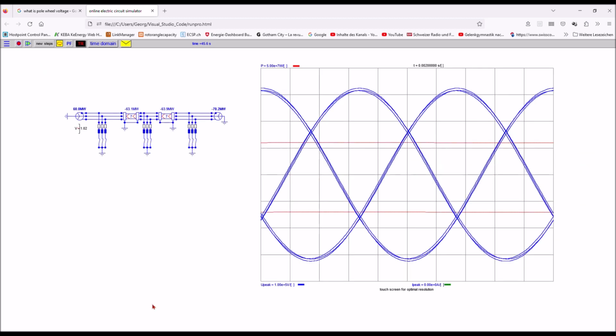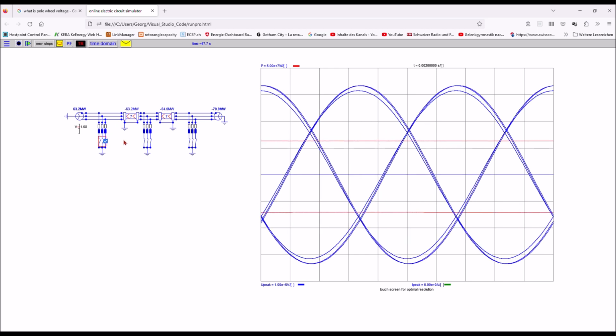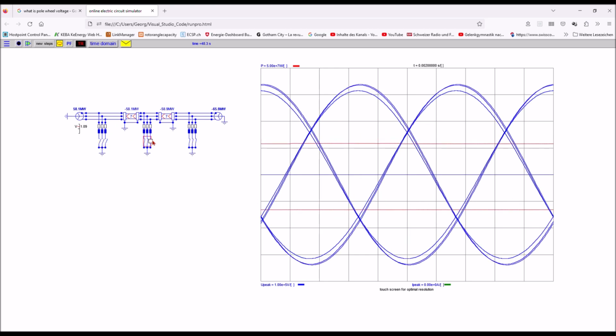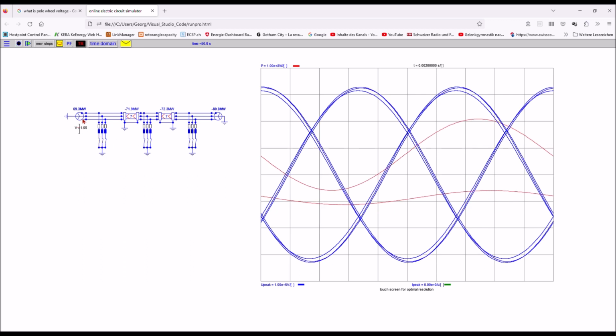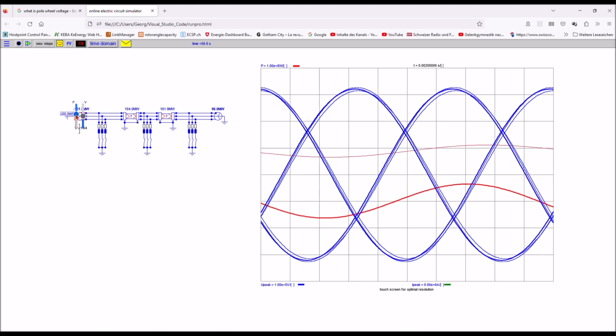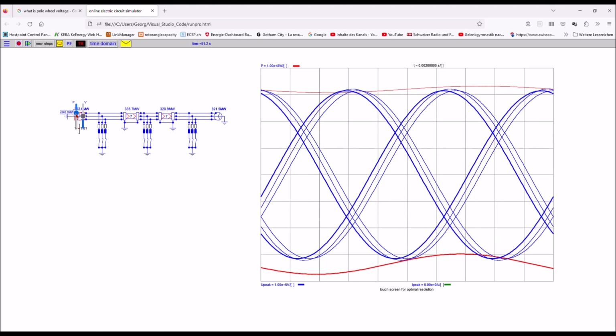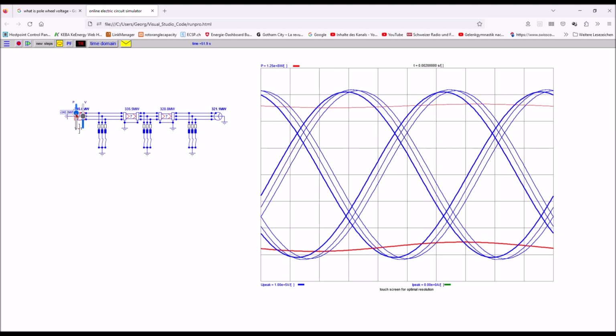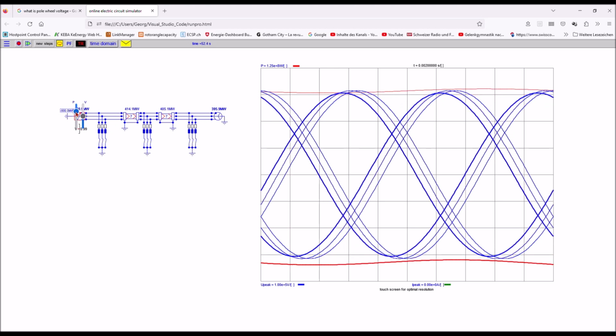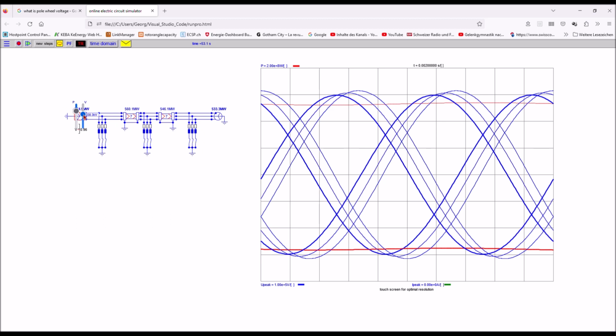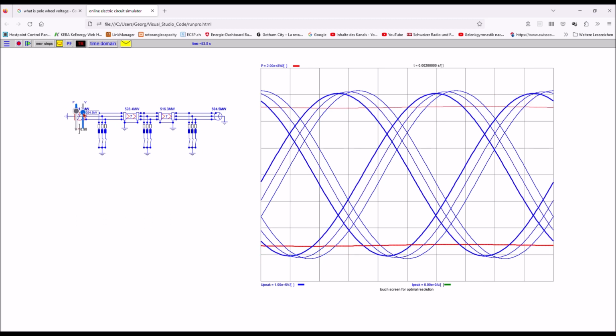Here is an example of a generator on the left side feeding power to an infinite bus over 2 200 km line segments. They are compensated by reactors. You can see the effect of switching on and off the reactors. So far the generator doesn't feed power yet to the system. Let's now feed power by increasing the generator torque. You can observe how the rotor angle increases as well as the angle between the voltage of the sending and the receiving end of the lines.